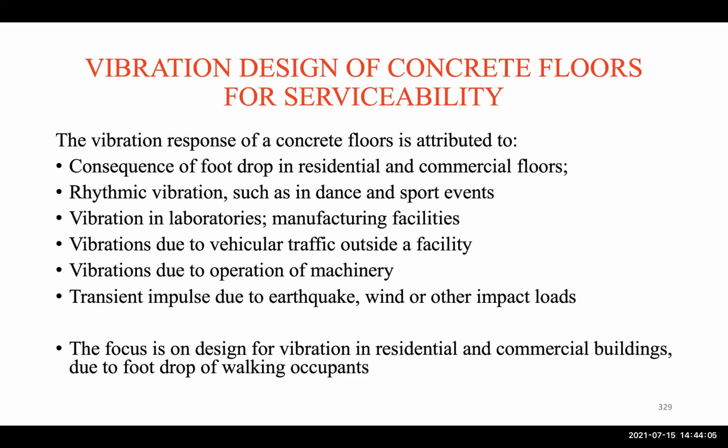This is, of course, a serviceability criteria. It's not a strength criteria. But if the floor is bouncing, then it will not be serviceable. It's not comfortable for the occupants, especially in open office buildings that have cubicles without full height partitions, right? So the vibration, of course, depends on the application that we use.